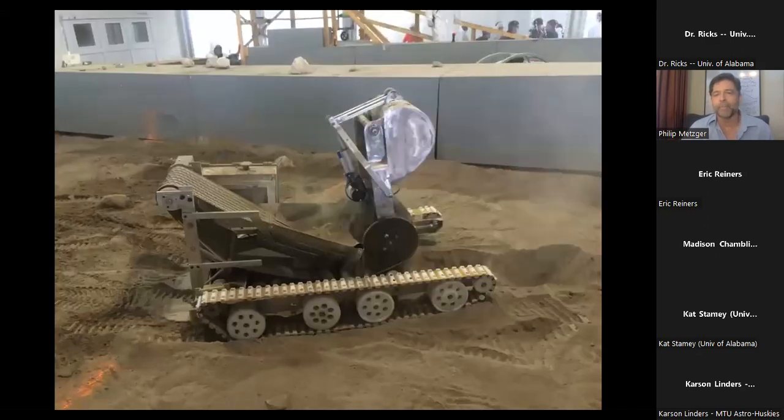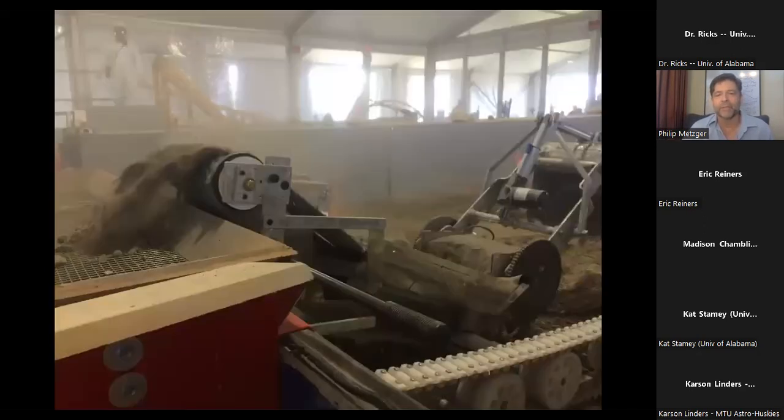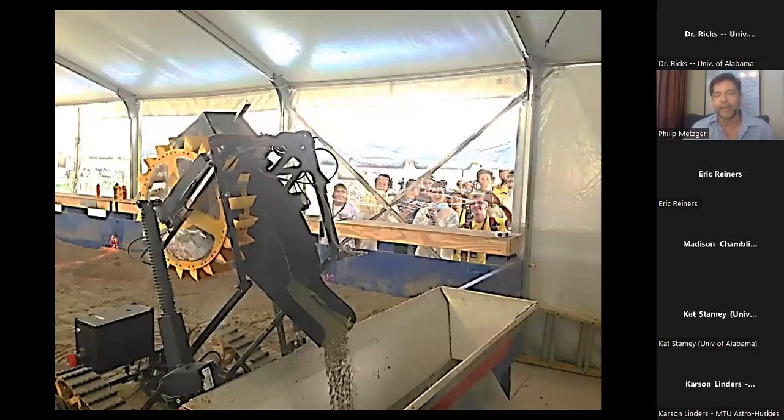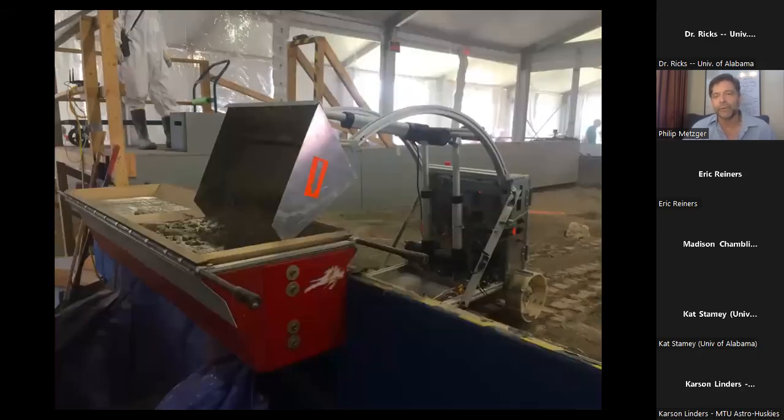Okay, bucket ladders. Okay, this was a general talk on the robots. So talking about dumping, you can see that that angle there looks like about 45 degrees, but even so, it's not really enough. And the soil can hang on the robot. So teams would have to try to jolt forward and back to get the soil loose. A tip for you is just use a steeper angle. Okay, steep angles are good.